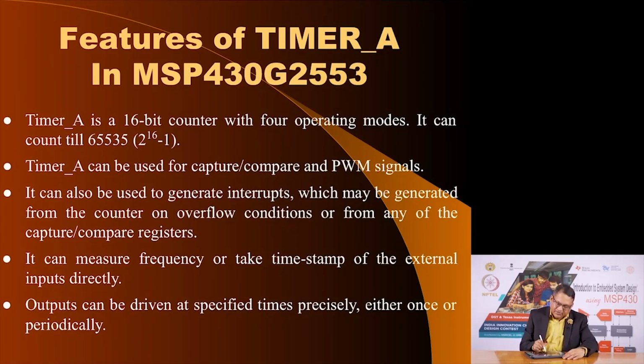The timers can be used for capture and compare functions. I will come to this feature shortly, and it can also be used to generate pulse width modulated signal, which we briefly mentioned in a previous lecture. The timers can be used to generate interrupts on a timely fashion. You want to generate an interrupt every 1 second or every 100 milliseconds. You can employ a timer by appropriately programming it. It can generate very accurate interrupt events, which you can use to do some housekeeping jobs.